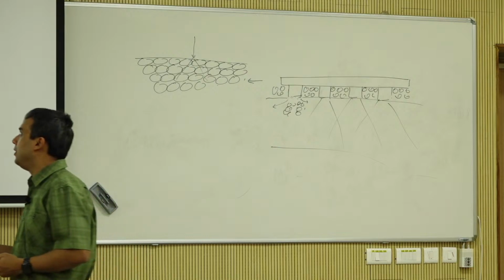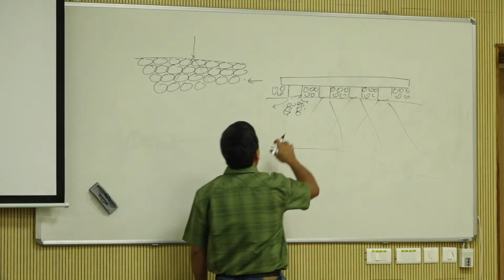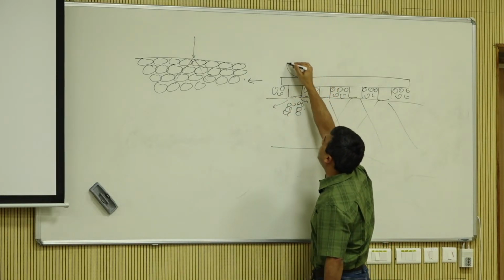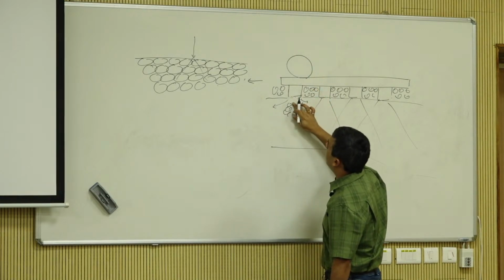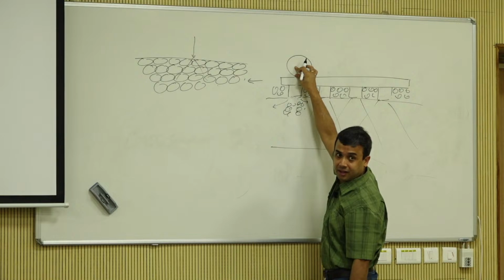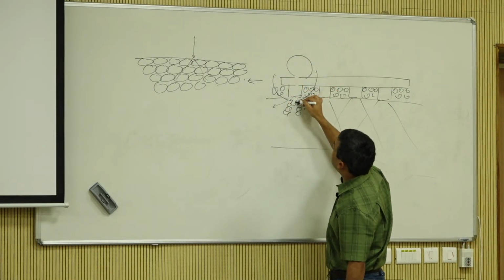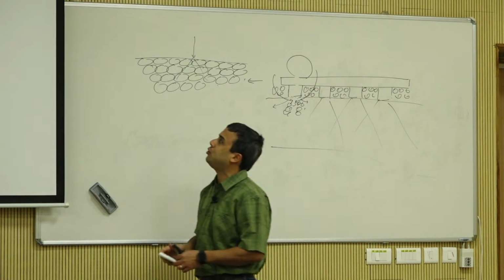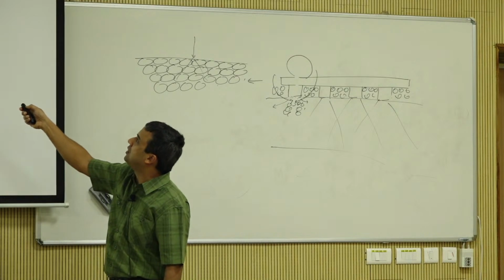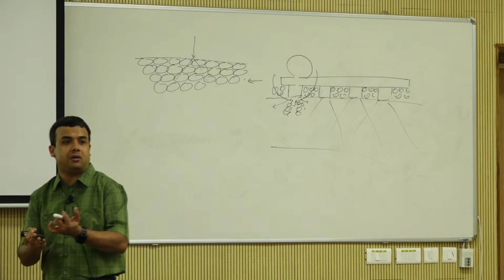It's pretty strong, right? So one of the approaches to avoid this excessive deformation and the increased dynamic loading when the train goes through this is to lift the track and insert additional material that is almost like pea gravel, very fine, uniform-sized gravel or rocks, to create a support layer underneath.